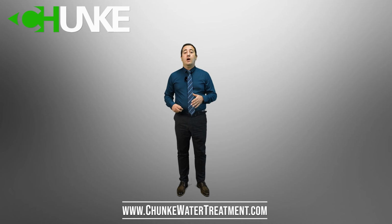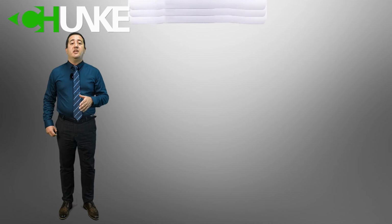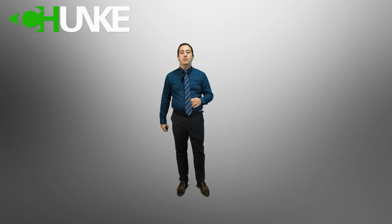Such as in our 6000 liter per hour reverse osmosis system example, we found that we need 6 RO membranes. If we choose 2-element membrane housings, we need 3 membrane housings. Meanwhile, membrane housing and element vessel are the same thing, every country uses a different term for it.